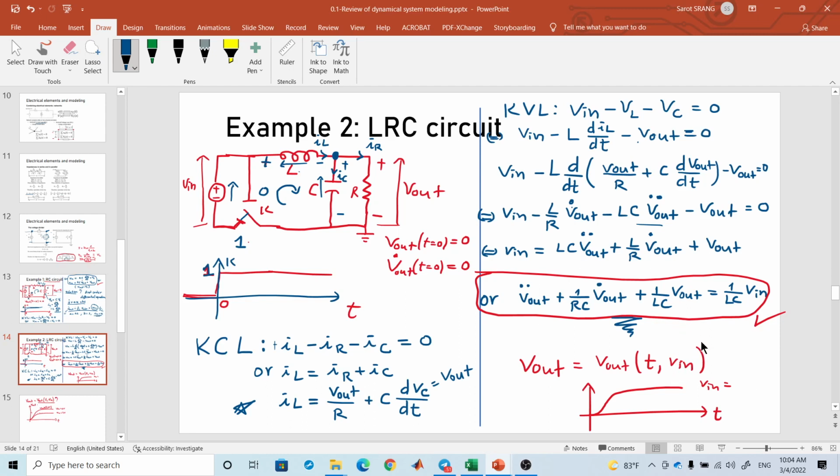So what is the behavior of this kind of dynamic equation? Again, you expect that the voltage of the capacitor should approach the input voltage, right? At first the charge is zero, so of course current flows very fast, but maybe not too far because you have an inductor here. The inductor resists the current at the initial moment. That's why you have this kind of shape. At the beginning, the inductor doesn't want the current to flow.